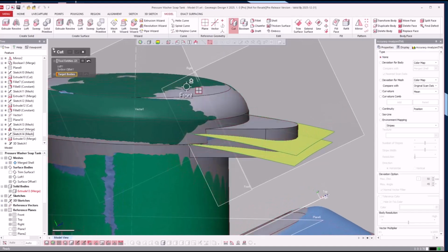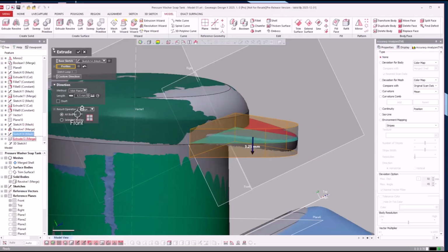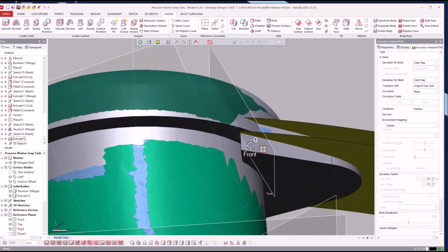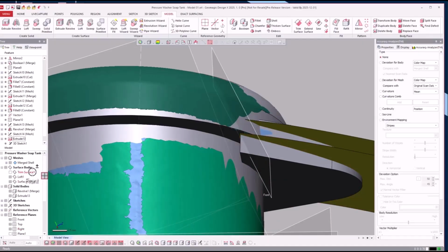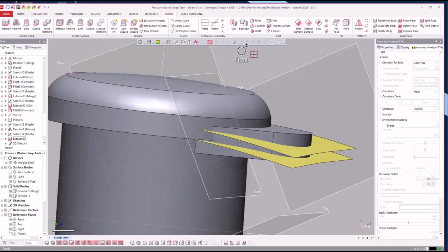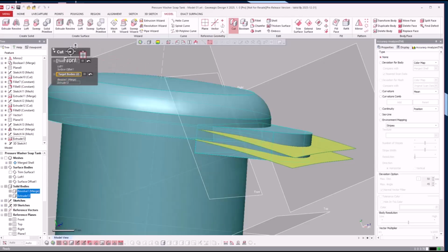And then here's one mistake that I made. So let's get out of that real quick. The new defaults for the software made this merge. So I have to open this up, change it to insert. And then the other thing is make sure that that completely intersects. I think it does. Let's just take a chance. Let it ride. Target bodies, this, next. Yes, it did not.